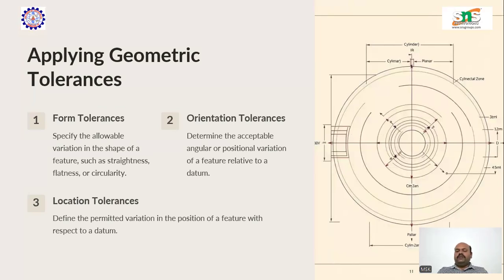So coming to the manufacturing part, for example, you want to manufacture an item which is 30 mm in diameter. You have to do facing. Am I right? When you do facing, you will not get the same size as mentioned in the drawing. Because of the man-machine method, there is a lot of difference in manufacturing dimensions from the accurate dimensions mentioned in the drawing.